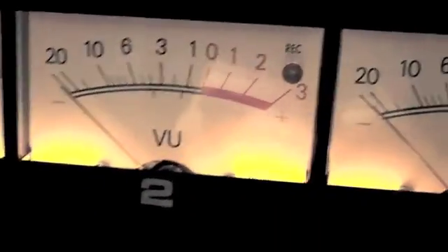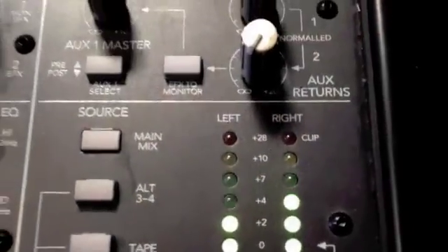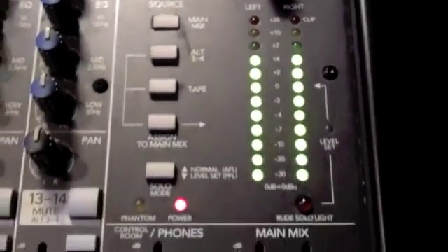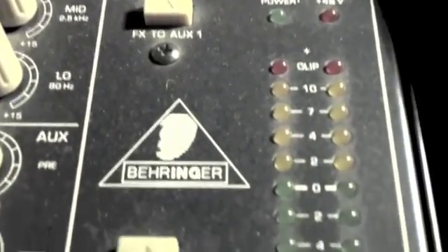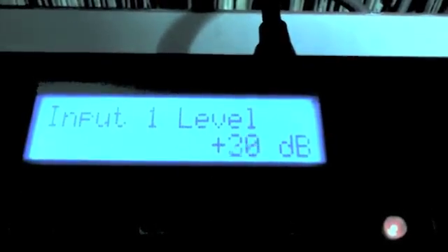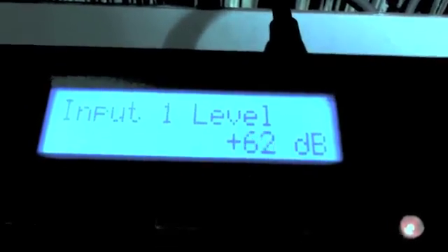The dB, or decibel, is purely a ratio that on its own indicates no specific value, only a ratio. When one of the aforementioned suffixes is added, it indicates that the ratio is referenced to an industry-standardized specific value at 0 dB. The reason for the decibel's logarithmic nature is to handle very large ratios with more reasonable powers